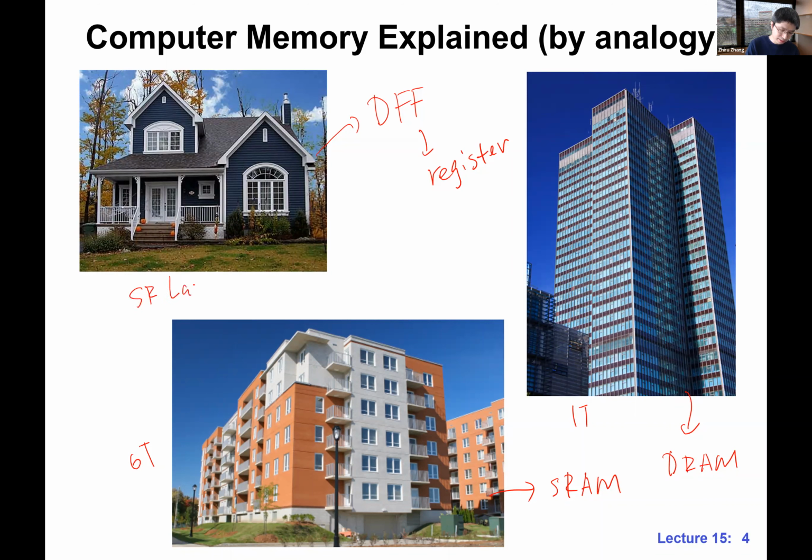Let's say this is SR latch. Yeah, 2 gates, very good. Let's say we have a NAND gate, a 2-input NAND gate. We have two-input NAND gates. How many transistors do we have per NAND gate, including both PMOS and NMOS? 4, very good. In case you already forgot, make sure you refresh your mind. Take a look at the CMOS lecture. For NAND gate, we have 4 transistors per 2-input NOR or 2-input NAND.